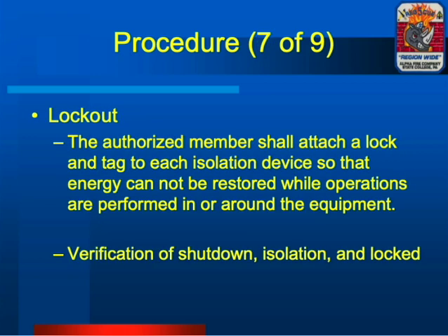So what is lockout? Okay, so then we're going to move on to lockout. The authorized member shall attach a lock and a tag to each isolation device so that somebody can't walk up to it and operate that piece of machinery or turn the machine on. Do you see there's an issue with just turning a switch off?